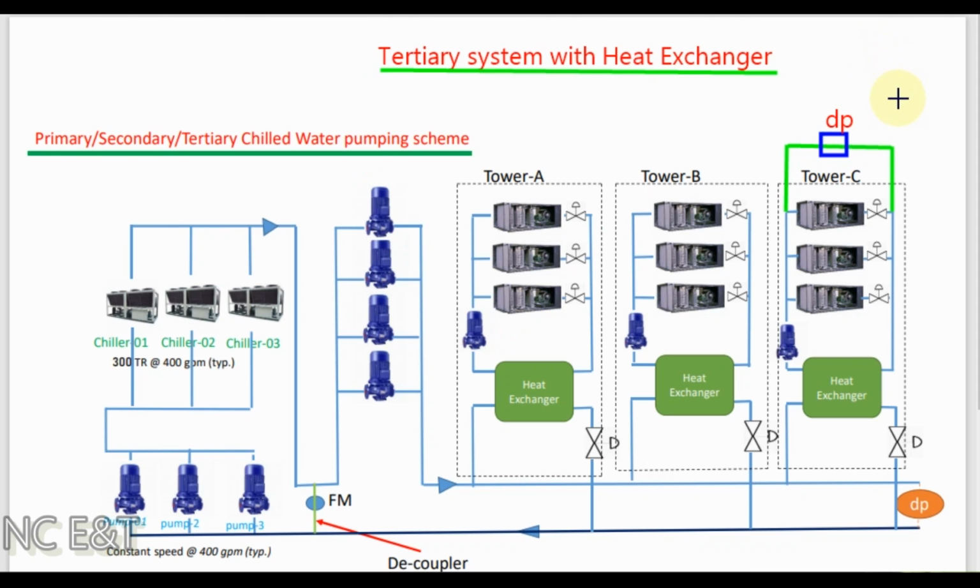In this type of chill water piping system, normally we have a big quantity of chill water to flow through the secondary chill water piping network. In order to save cost, we try to minimize the diameter of the chill water pipe in the secondary loop, and to achieve this we select the chill water flow at maximum possible pressure and maximum possible delta T temperature according to the equipment available.